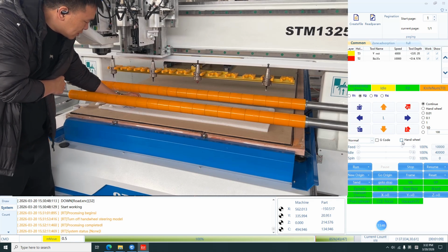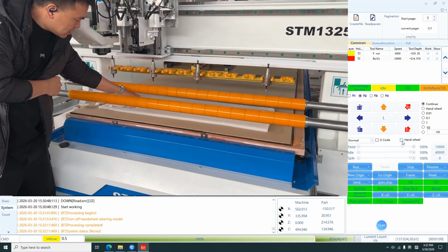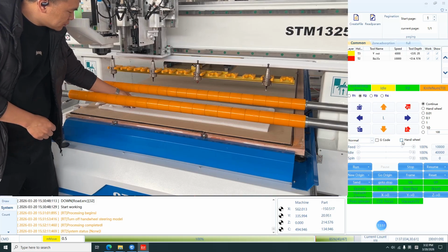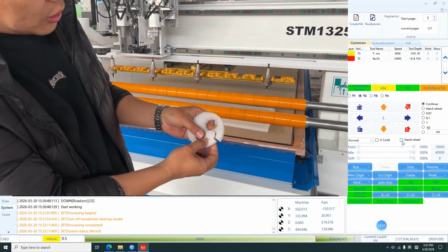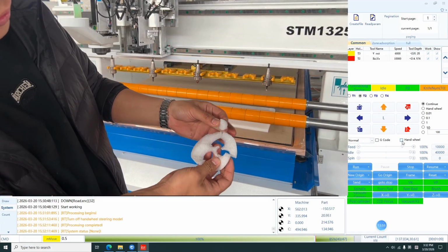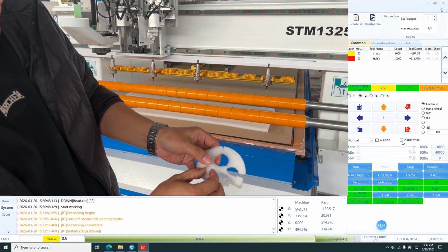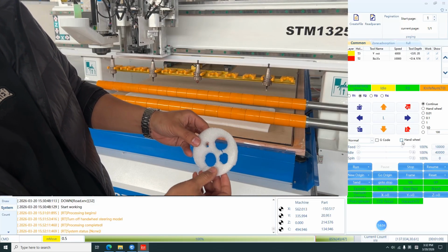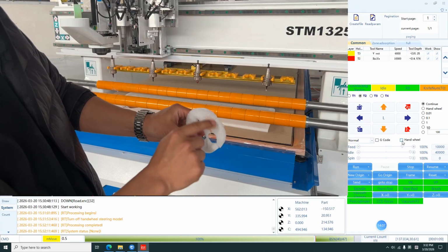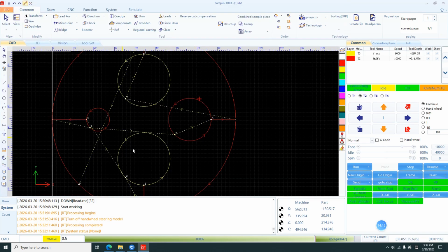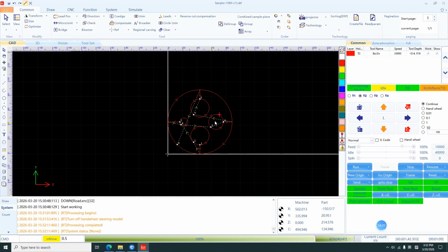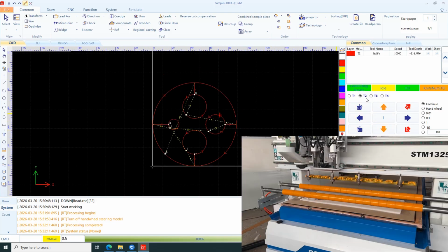After the cutting was complete, I removed the material and discovered that it had not been cut all the way through. The Z-axis 0 point for the oscillating knife needs to be lowered by 0.5 mm. After completing the cutting, I realized that because the circle was too small, using a V-cut in this area did not yield good results. I tried a subsequent cut. I removed the V-cut operation and changed all the lines to red, using the oscillating knife for cutting.